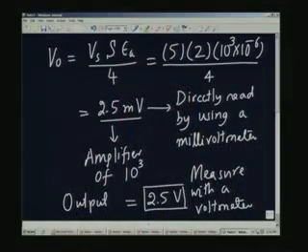Now, we will look at one or two important things which you have not looked at till now. If you remember, when we were talking about temperature measurement using resistance temperature detectors or RTDs, we talked about something called self heating. Self heating is because a current is passing through the resistance, and because of the Joule heating, a certain amount of heat is produced, and depending on the rapidity with which this heat can be lost from the detector, it will attain a temperature which is higher than what it should be. So, self heating is going to change the resistance of the detector because of the temperature change, and a strain gauge is nothing but a resistance.